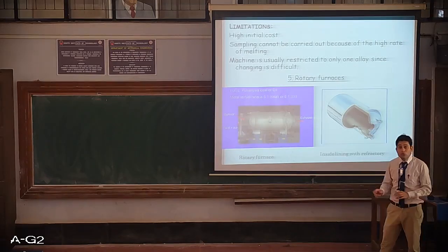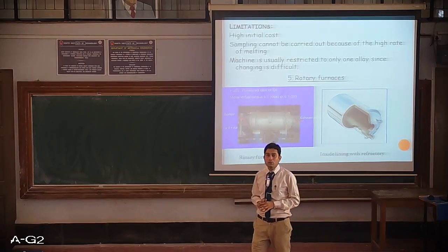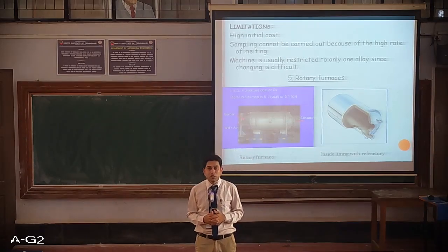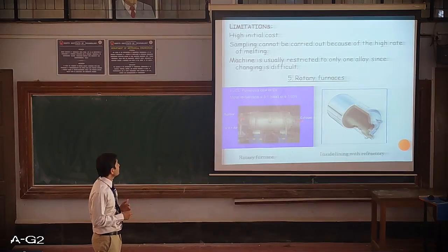What are the limitations of this type of furnace? The limitation is the high initial cost. So if you wish to take an induction furnace, you have to shell out a huge amount of money. That's why high initial cost is there. Sampling cannot be carried out because of the high rate of melting.